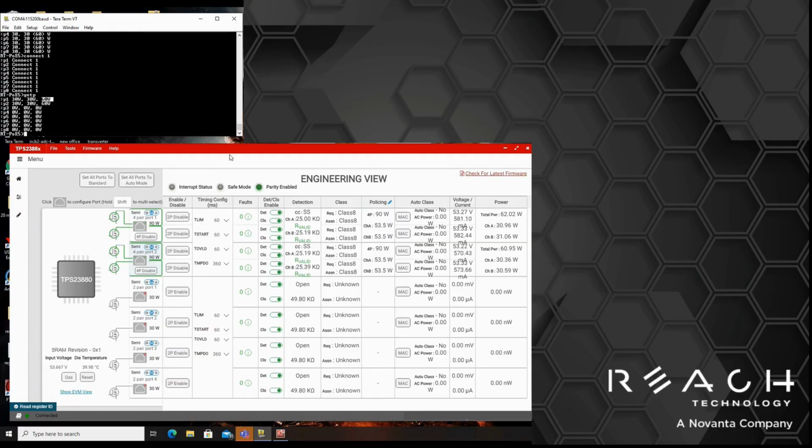That's what it's measuring. Watts are always rounded, and that's partially just because of the imprecise nature of doing power as opposed to current. Also, we round it a little bit because when there's a cable involved, you're dissipating power in the cable, and when we round it, it reduces confusion as to what's actually being drawn. We have the current measurement, where you can get a much more accurate picture of what the current draw is, which is what the get I command does.